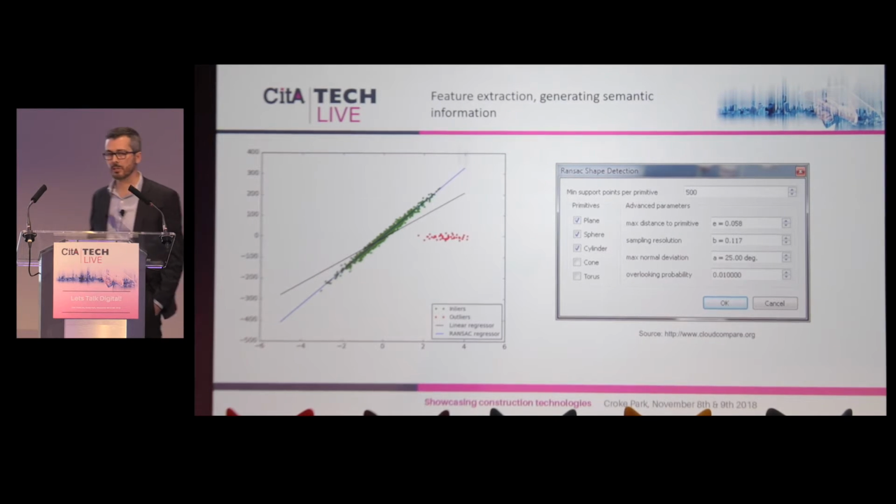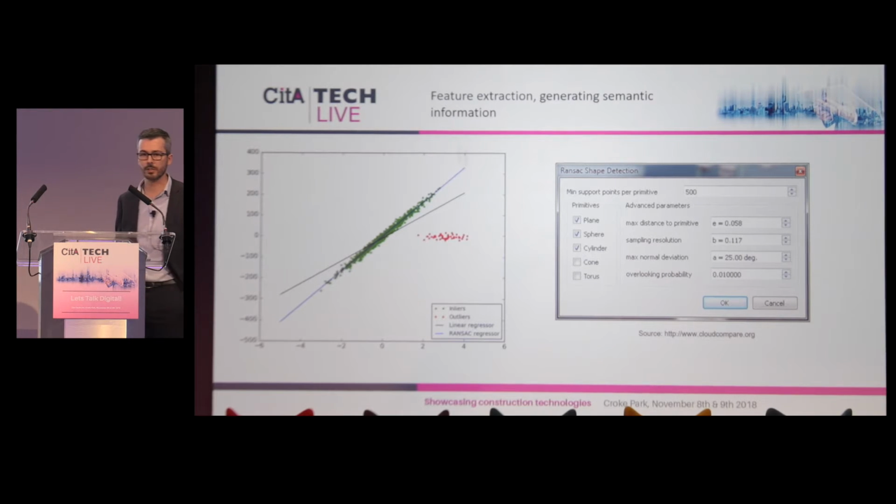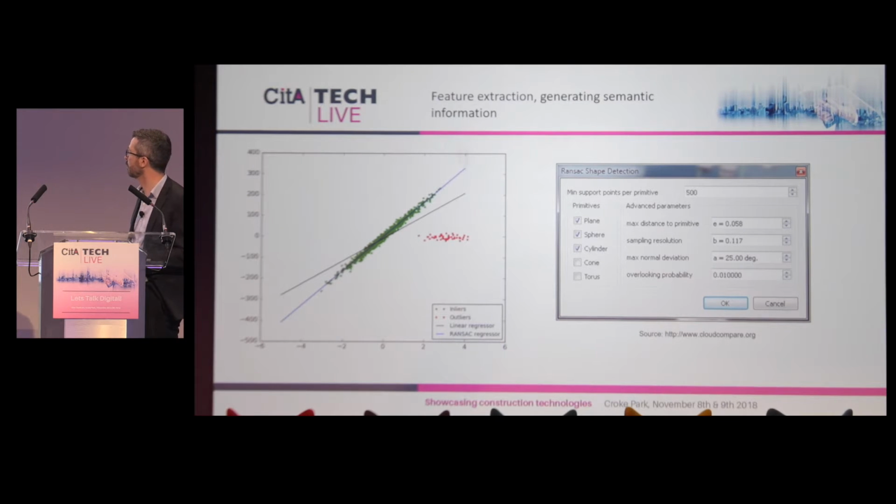What is actually happening in the background? It's just a regression technique. Some of the plugins have linear regression, but we can also use nonlinear regression. RANSAC is one of the known algorithms for that. Essentially, it removes outliers in an iterative process and allows us to obtain a more relevant data set that will exclude any spurious data that might be in the point cloud.